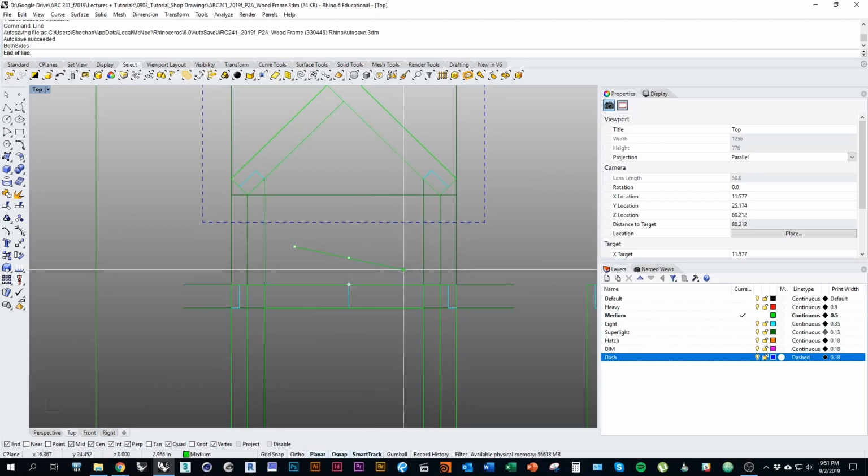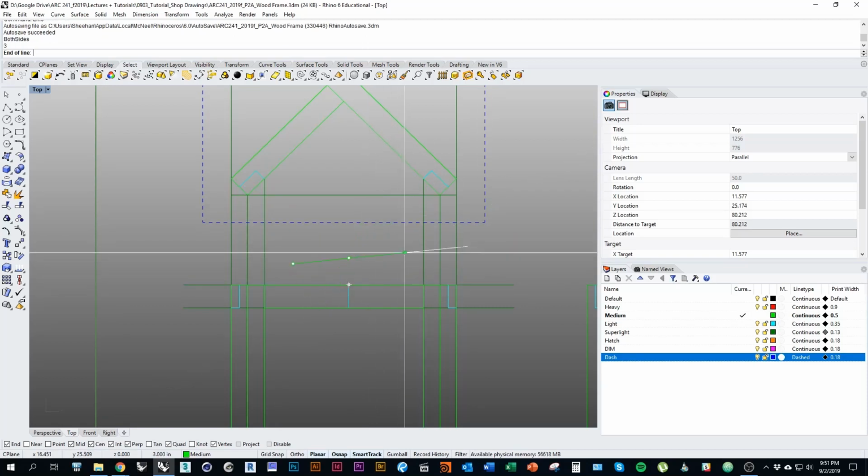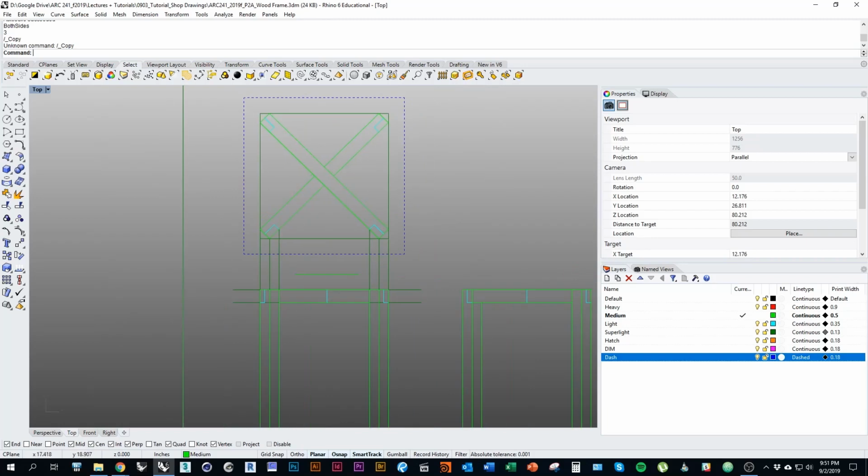Now I'm going to type in 3. So 3 in both directions makes a 6-foot straight line. Hold shift to snap to ortho. Okay, so now I've drawn the flat part of the seat.